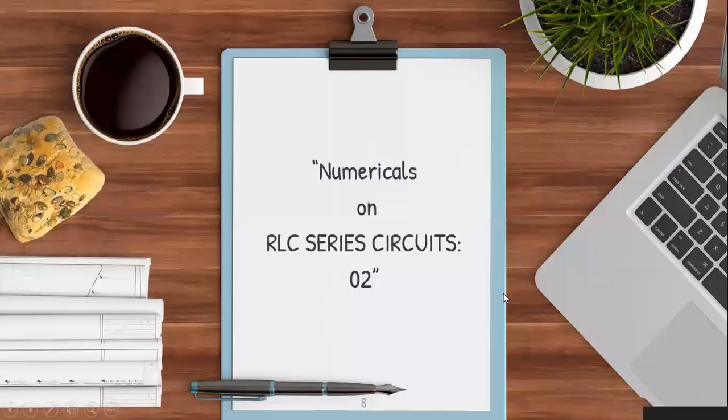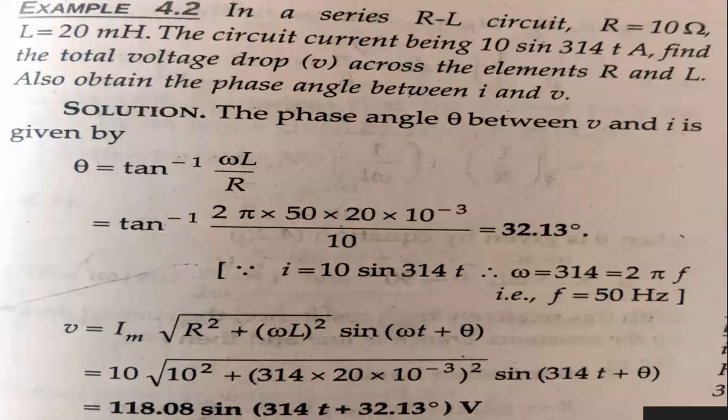Now come towards the next numerical number 2, which is on the steady state sinusoidal RLC series response. So what is that? Note down, all of you. In a series RL circuit, R is equal to 10 ohm, L is equal to 20 millihenry. The circuit current is 10 sine 314t ampere. Find the total voltage drop V across the elements R and L. Also obtain the phase angle between the I and the V.